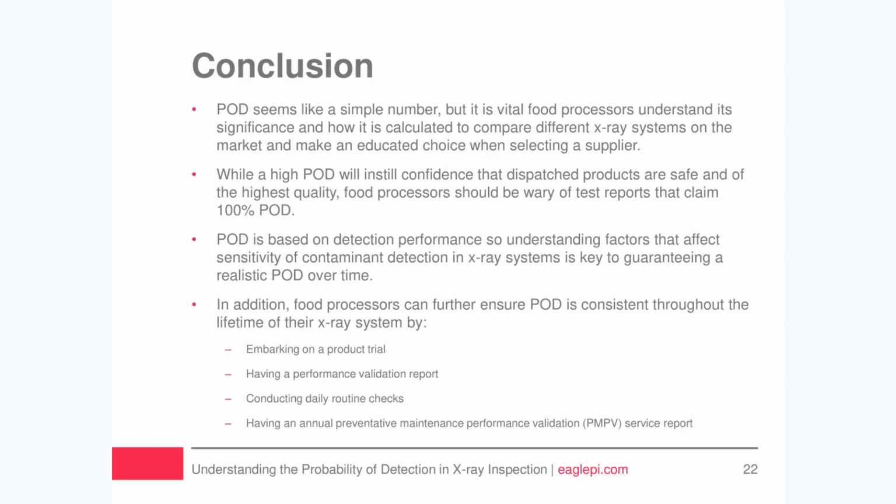While a high POD will instill confidence that dispatched products are safe and of the highest quality, food processors should be wary of test reports that claim 100% POD and equally 99% POD, as we've touched on earlier, very, very difficult to prove. POD is also based on the detection performance. So understanding factors that affect the sensitivity of contaminant detection in X-ray systems is key to guaranteeing a realistic POD